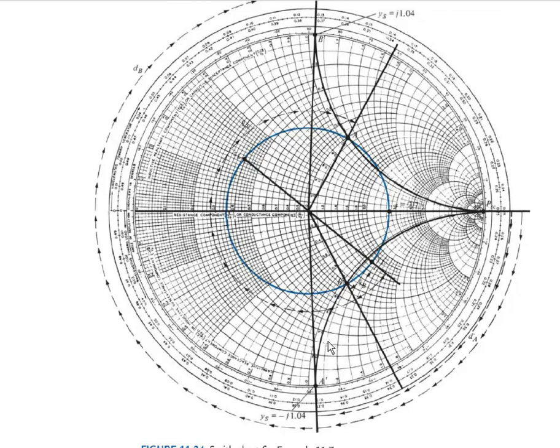From this origin you can extend a straight line to this A dash and this B dash. After extending a straight line to A dash and B dash, you can measure the stub length from PSC. This point is PSC, in the anti-clockwise direction to B as well as A. We can see this measurement from here PSC, or we can measure this distance in the clockwise direction also.